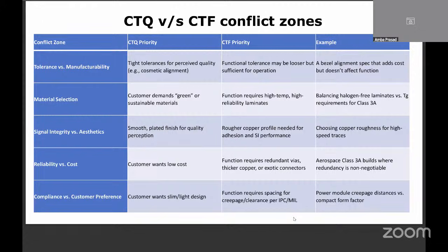But this is more or less solved because all these standard bodies like PCI-SIG or somebody, they have defined everything. They have defined the connector, they have defined the assignment, they have defined the chassis width and the depth and the height. Mostly this kind of architecture, people go for a 2U type of height. They can do it in 1U, but they're going for 2U because of thermal issues. 2U is very easy to cool. Yeah, you know better.